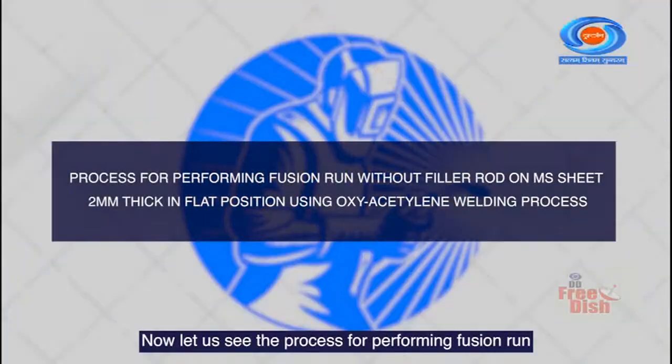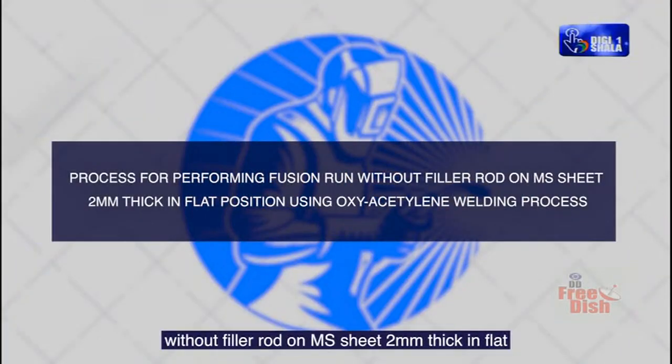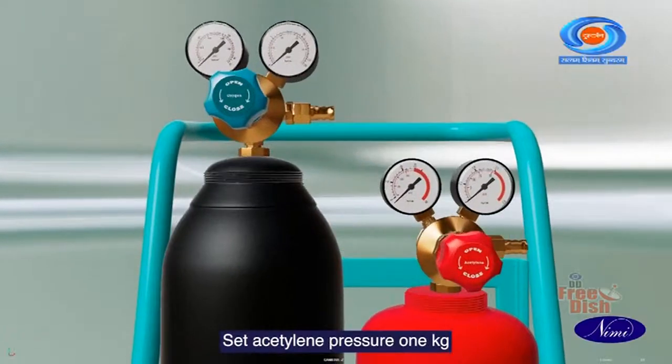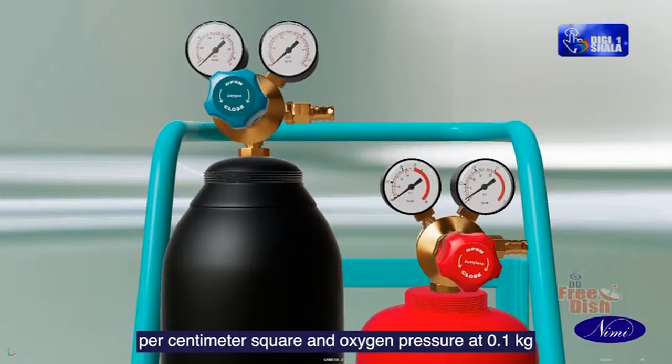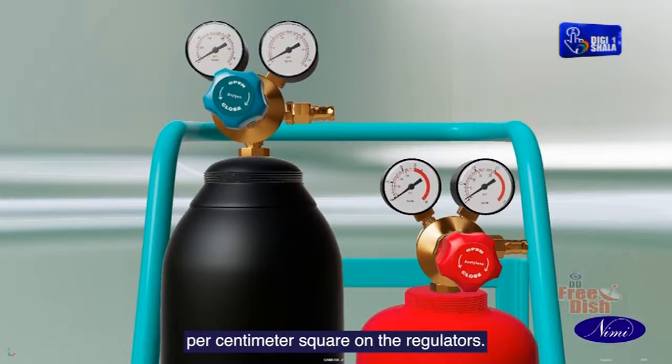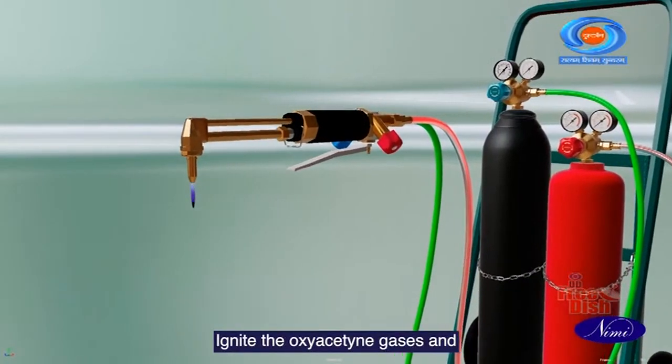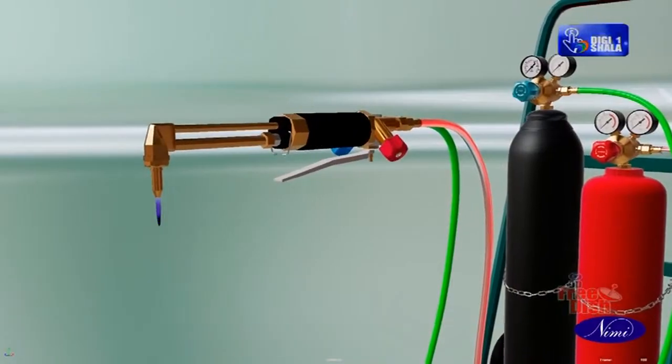Now let us see the process for performing fusion run without filler rod on MS sheet 2 mm thick in flat position using oxy-acetylene gas welding process. Set acetylene pressure 1 kg per centimeter square and oxygen pressure at 0.1 kg per centimeter square on the regulators. Ignite the oxy-acetylene gases and adjust the neutral flame.